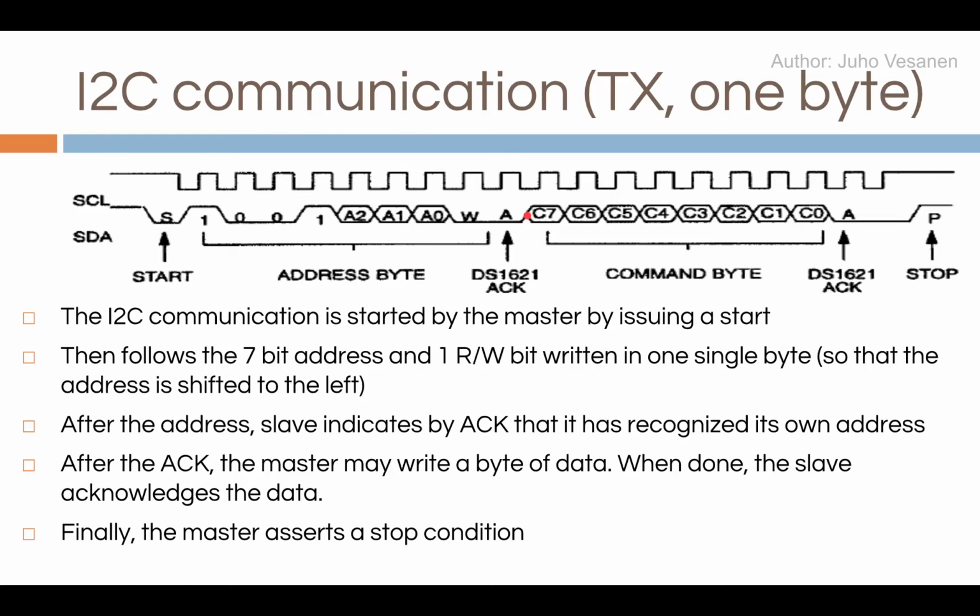Next, the master writes a command byte, which is just 8-bit data, and then again that device must acknowledge it, and then stop.